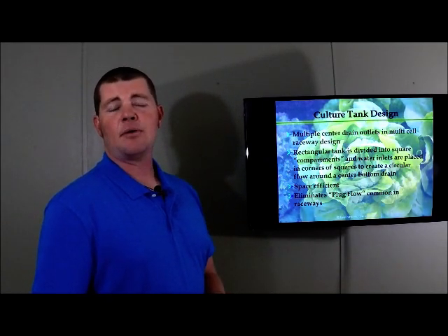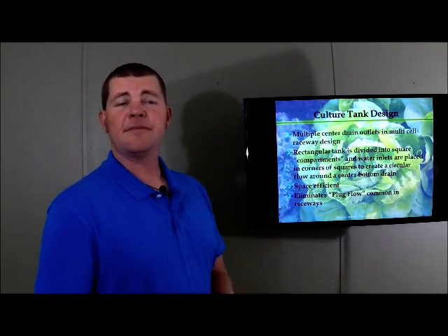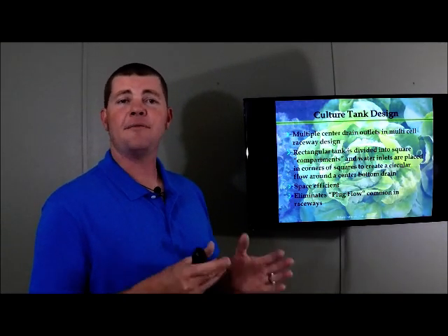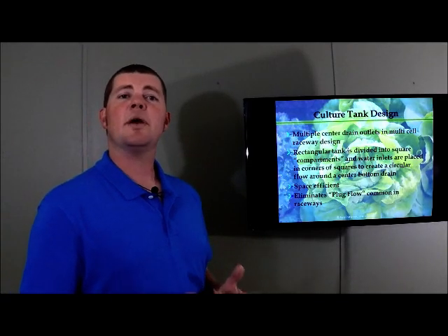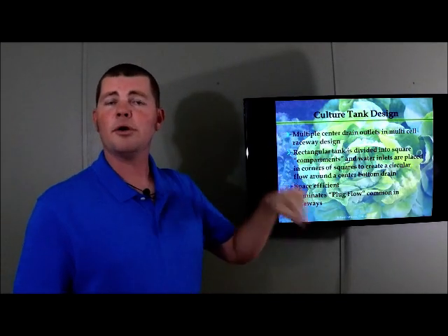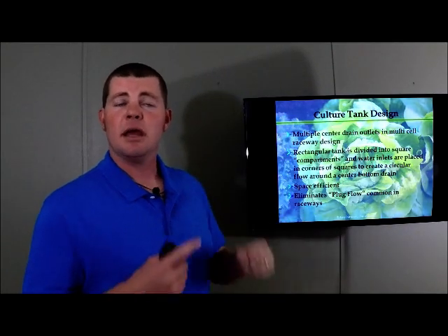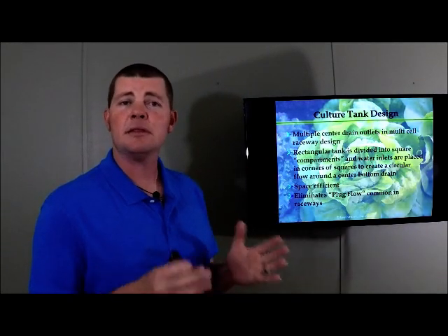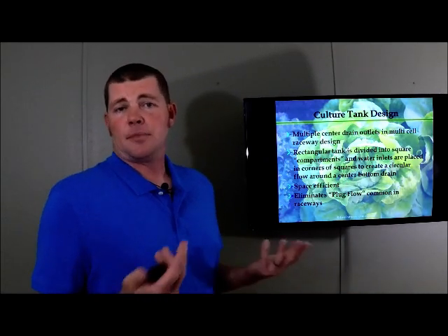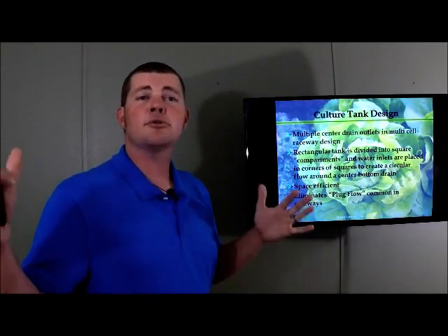So if you think about a 5-foot by 20-foot rectangular tank, if we divide that up into 4 5-foot by 5-foot compartments, then we have 4 squares. Each one of those squares, we would put the water outlet into each of the 4 corners of the square. Each outlet would point towards the next outlet, and that would create a circular velocity within that square. And then we would put a center bottom drain in that square, creating, theoretically, a circular tank within that square within the larger rectangle.